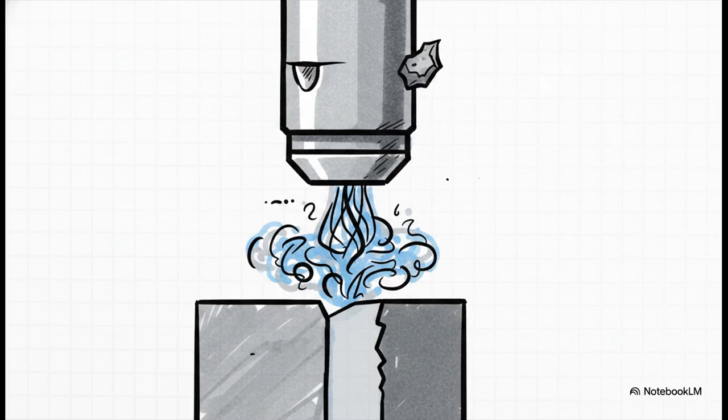If even a tiny metal clipping gets stuck inside it, or the nozzle gets dinged during a collision, the gas flow instantly becomes turbulent. And the result? You get an asymmetrical cut. One side of your part looks brilliantly smooth and perfect, while the adjacent side looks completely rough and jagged. All that high wattage means absolutely nothing without strict daily maintenance.